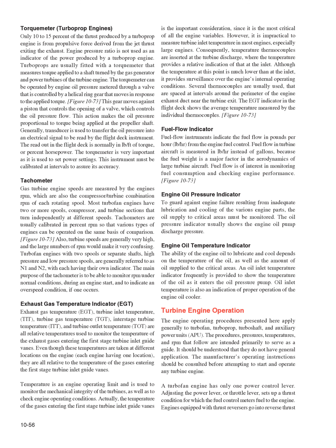Figure 1073, engine oil pressure indicator. To guard against engine failure resulting from inadequate lubrication and cooling of the various engine parts, the oil supply to critical areas must be monitored. The oil pressure indicator usually shows the engine oil pump discharge pressure.